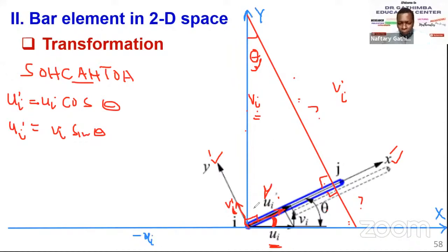The same case, if we extend it downward, it will be negative. So now from this point, we need just to use a simple triangle, a similar triangle the way we have this on this side, and then simple geometry, we can resolve the displacement on the vertical axis. We want to resolve the vertical displacement in the local coordinate system to both vertical and horizontal in the global coordinate system, resolving forces.